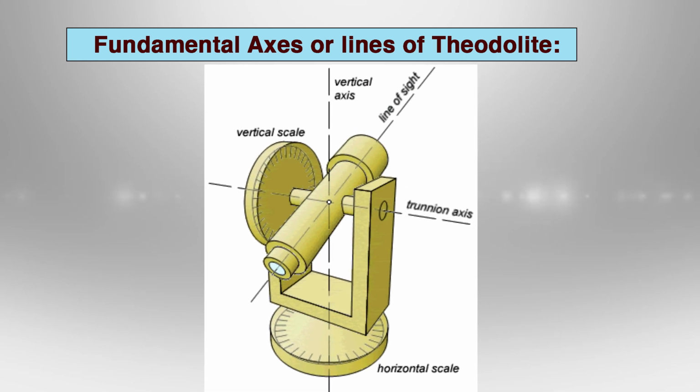Again look at the components of the theodolite. You will find the horizontal axis mentioned; it is nothing but the trunnion axis. We have come across this term, trunnion axis or horizontal axis, numerous times in our discussion. Remember that the transit of the theodolite takes place about this axis only. So, the next line is the line of collimation. We have already defined it.